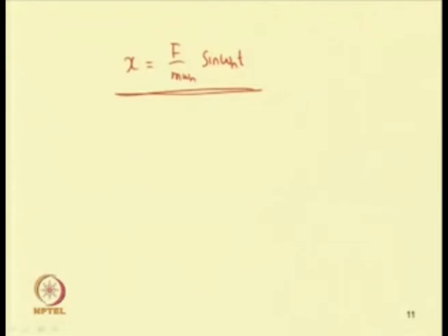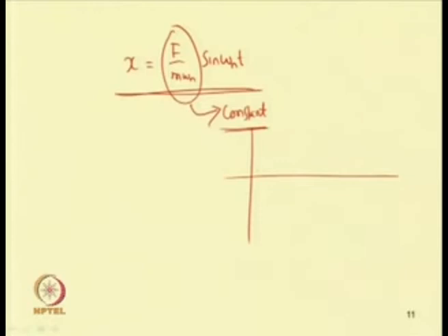So, this is the solution. Here the amplitude of the response, that is f by m omega n, is constant. But as we will see in this lecture, in case of nonlinear systems, the amplitude of the response is not constant. It will vary with the frequency of the system. In this case, the resulting solution has f by m omega n as a constant factor, so the system will vibrate with constant amplitude.